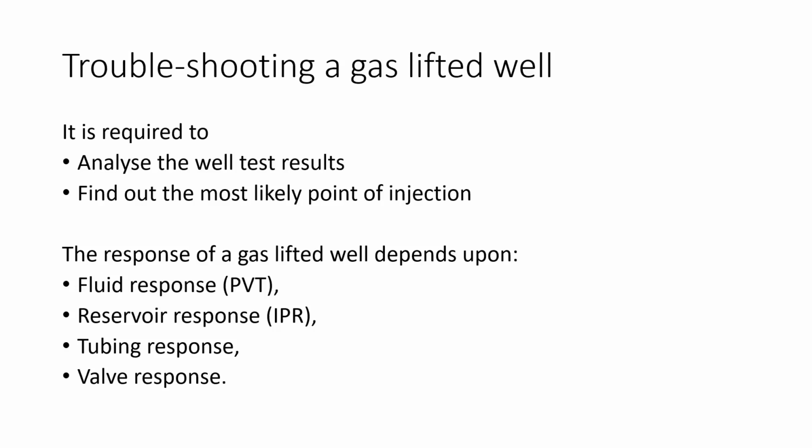So that's why these 4 important variables are fluid response, so the PVT, and then reservoir pressure, the IPR data, tubing response, and the valve response. These 4 variables are very important to play with in a gas lifted well. So in order to incorporate all these 4 variables, a quick